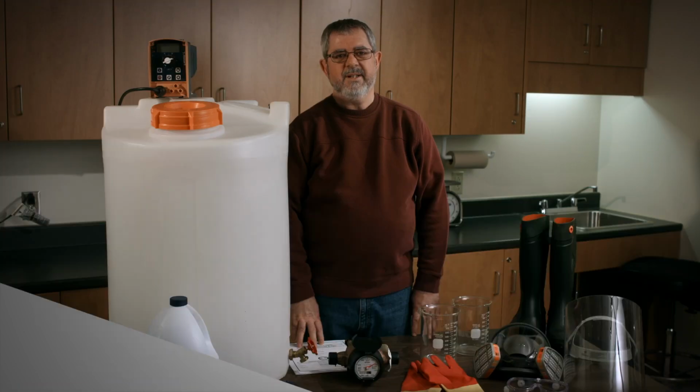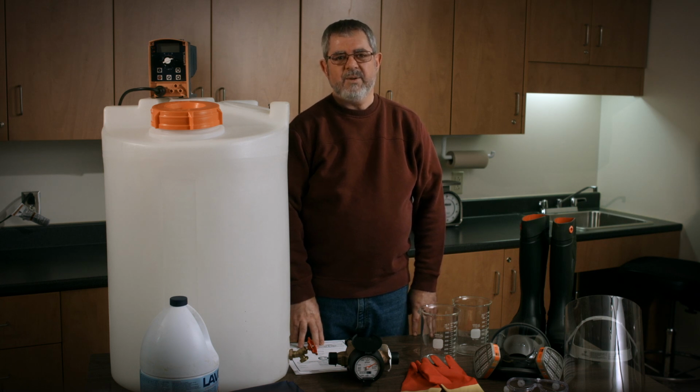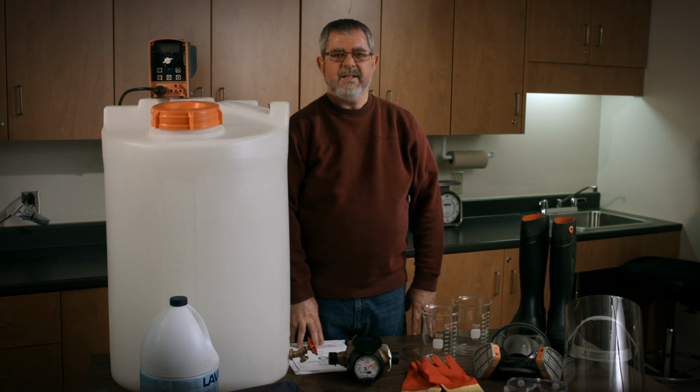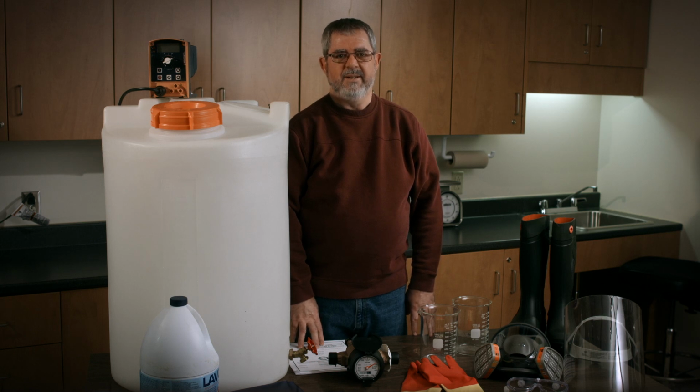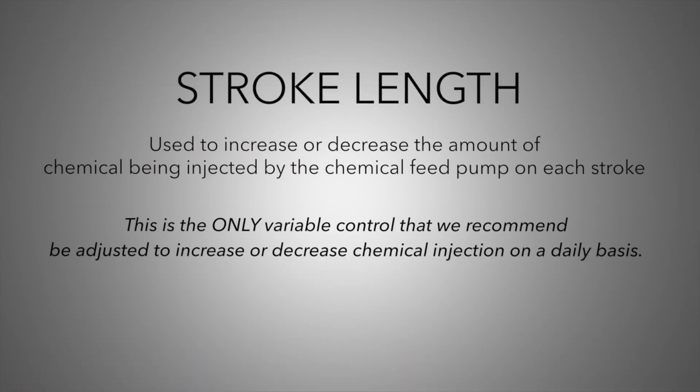With systems of varying flow, a flow meter is used to automatically adjust the pumping rate of the chemical feed pump. This is done to match flow variations in the water distribution system, such as low flows experienced overnight and high flows experienced in the morning. When the flow in the distribution system is uniform, the pumping rate can be held constant.